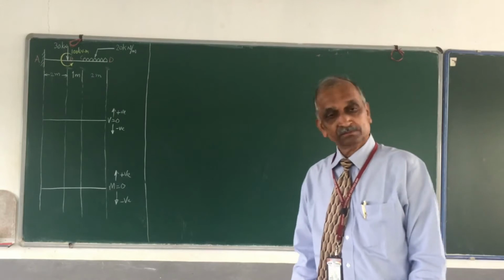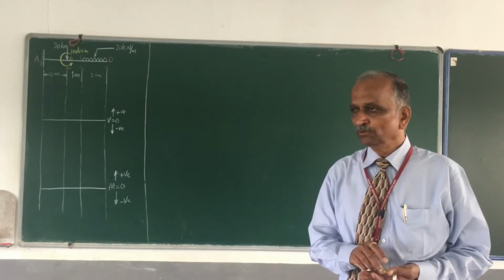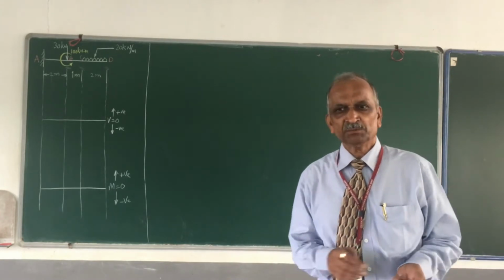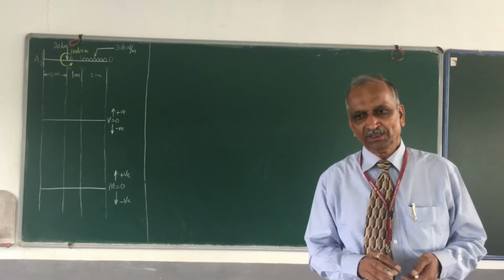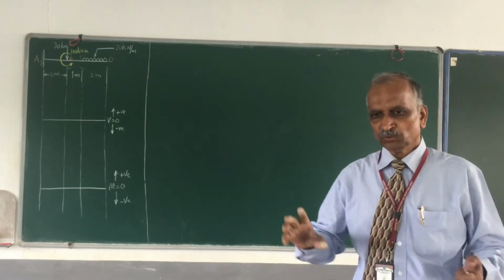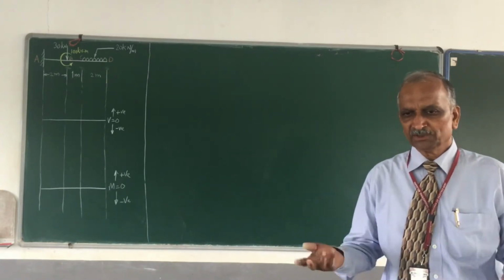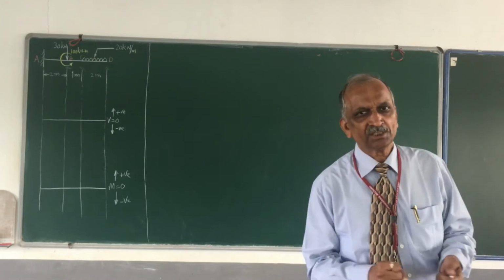Welcome you all for another session on bending moment and shear force diagrams. We all know what it means by shear force. It is basically a force at the section of a beam which is developed by the material at that section to keep the portion of the beam in equilibrium state. And similarly, bending moment is also the moment generated by the material.